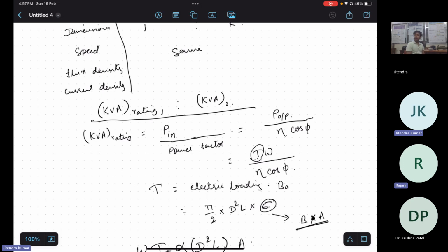Okay, we used to use two wire diameters, 1.5 with two parallel paths like that. 1.5 mm of wire diameter, you are saying, right? 1.5 and 2 also. Just recently, I designed one with a 2 mm wire diameter. While doing the winding of 2, it's very difficult to keep a 50% slot fill. They were unable to wind. They told that the turns must be less because of tension, and we took hand winding.